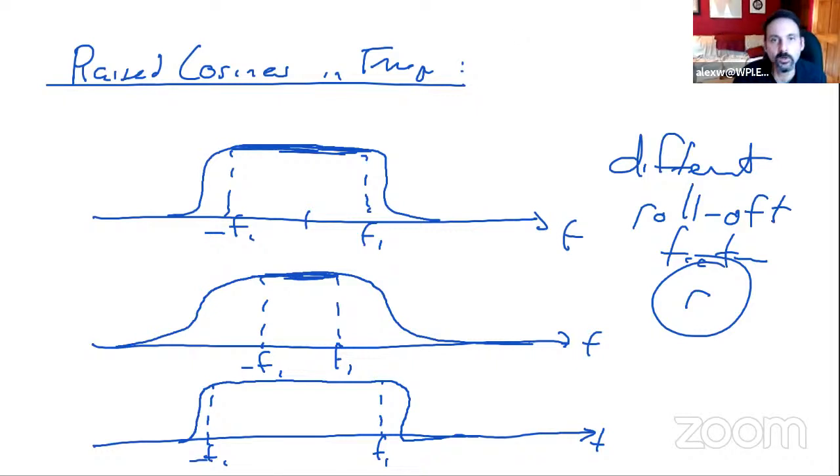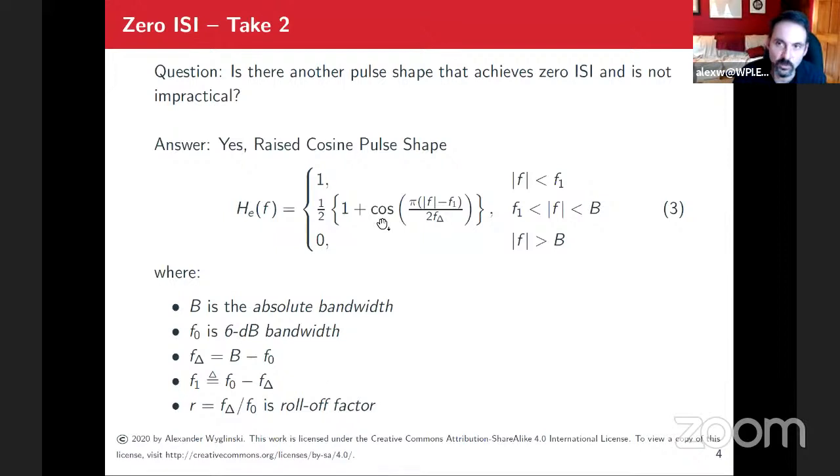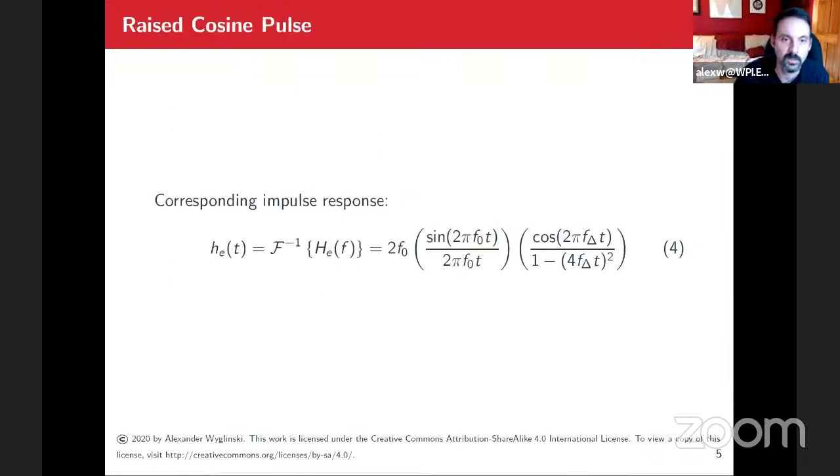So if we go over again to the expression here, this is the frequency domain representation. And this is its equivalent time domain representation, right? So if you're targeting your equivalent end-to-end h(t), h_T(t), h_C(t), h_R(t), to look like this in the time domain, this is what you'll be shooting for.